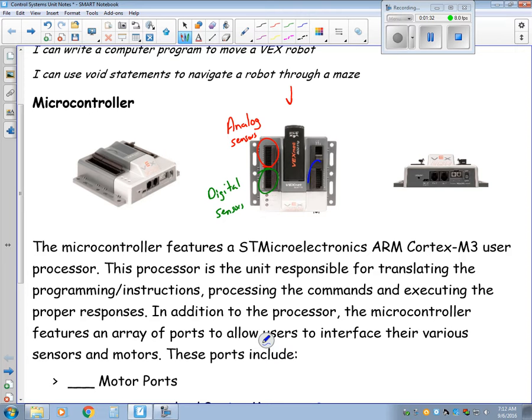On the right side here is where we have our motor ports. You will find 10. If I look at the front of the Cortex, right here you just see a little tiny plug. That's for our 9-volt backup. This port right here is for our main 7.2 volt robot battery. You will also see the on-off switch, and really that's all we need for this robot.